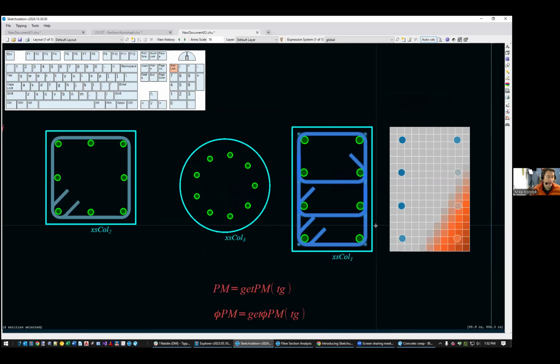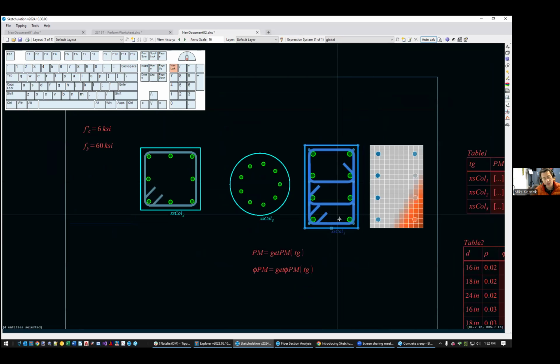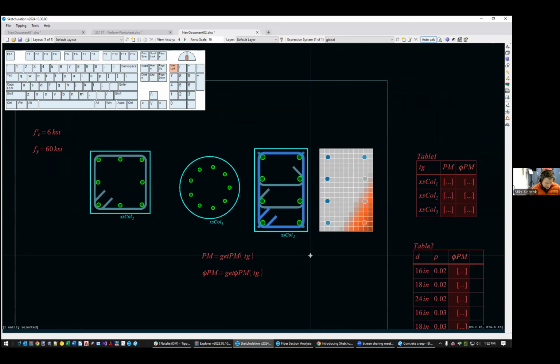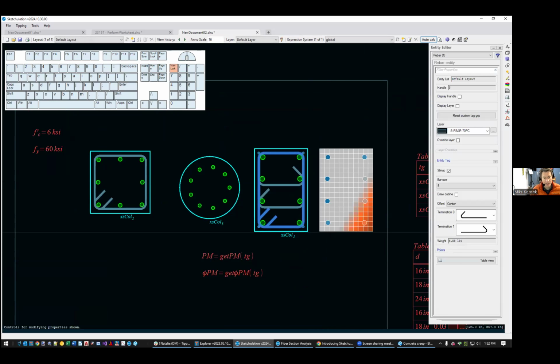Like I can get the amount of rebar in here. That's one of the things we'll do, we'll draw this up and try to give an estimate of the tonnage. So you can query this shape. It has a tag, and you can get the weight. Each of these has a weight associated with it. And in an expression, you can sum that all up.